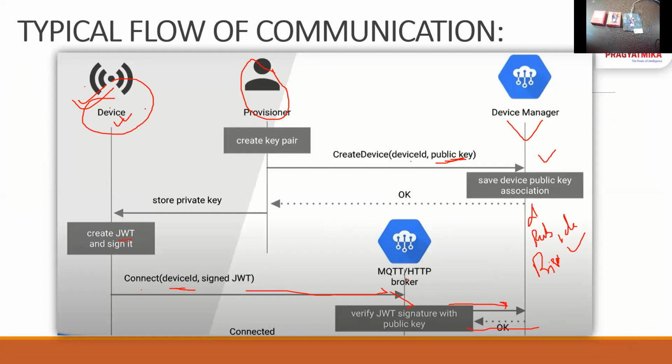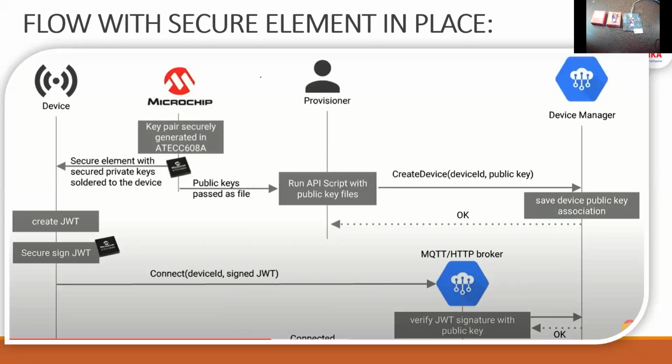But if we have an extra feature, which is hardware enabled, not software enabled, and that is there with our device, which can store our key pairs, our device IDs, our session keys, everything, then we can have a more secured environment, because this thing is separate from our device and is there on the device PCB, but cannot be compromised. This could not be compromised because it is not stored in the flash or the SRAMs.